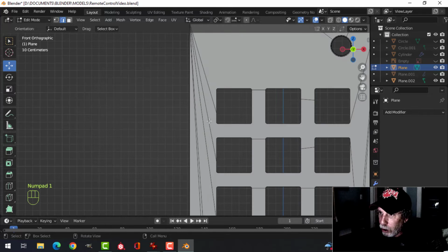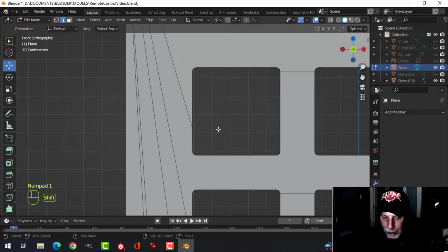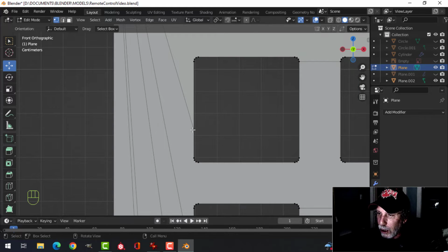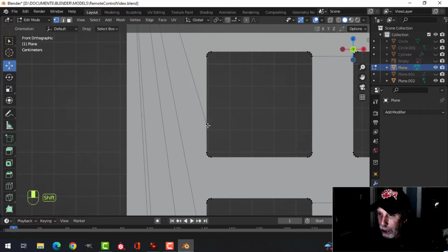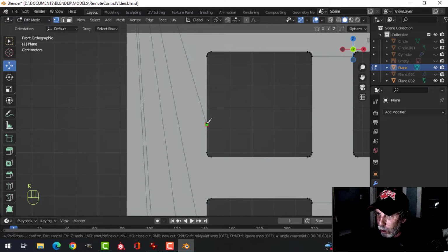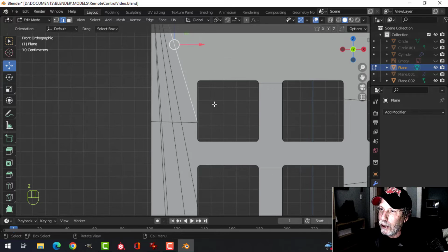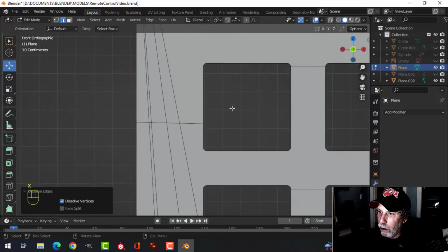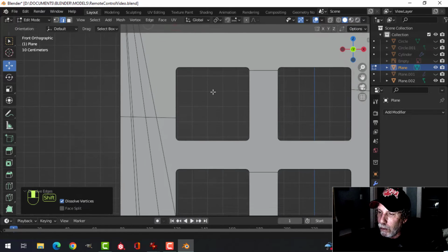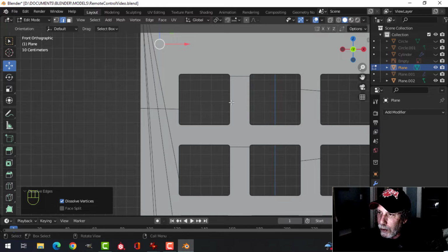So I'm going to look straight on this, and sometimes I like to press 1 for vertex selection, and you can see the vertex, so it wants to do it from here, and I'm okay with that. I'm going to press the knife tool, and I'm going to select that point. I'm just going to come relatively straight across. Doesn't even have to be perfectly straight. Press 2 for edge selection and select this one that was there before and dissolve it. And now this one says, well, I've got some support. I don't need the others.